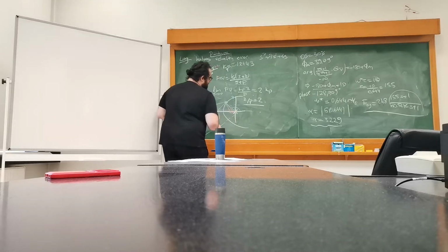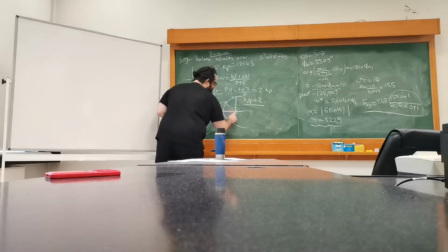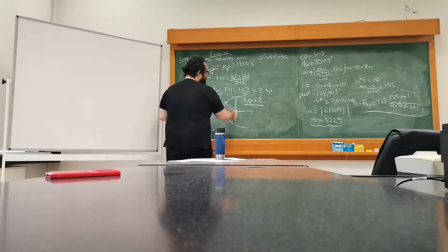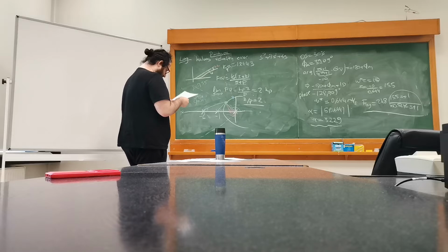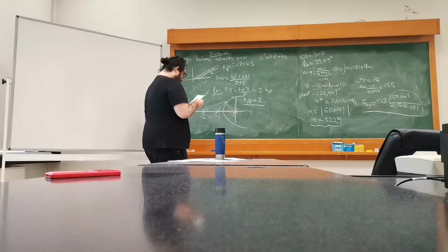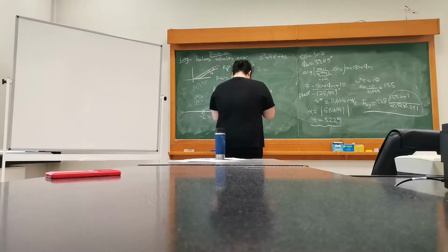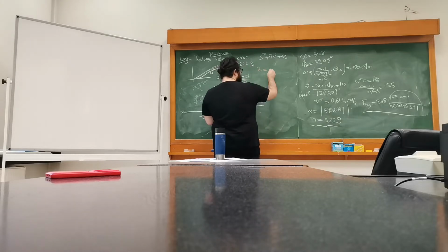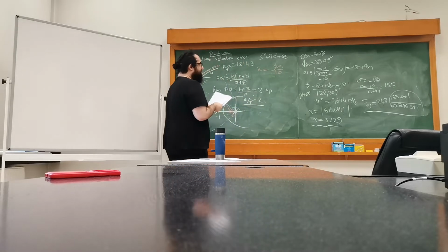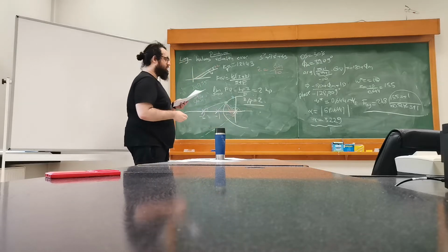So therefore, we can introduce, for example, the pole here somewhere, and the 0 here, and hope that the difference from here to here is not that big. So in order to ensure that, I'm going to push them towards the origin as far as I can. But it's dangerous because we will have another pole here. We have already one at the origin, so I should be a little bit careful. And therefore, for example, I can choose the 0. We have zeta omega n here. I can choose it 10th of the dominant value here. So this is zeta times omega n.